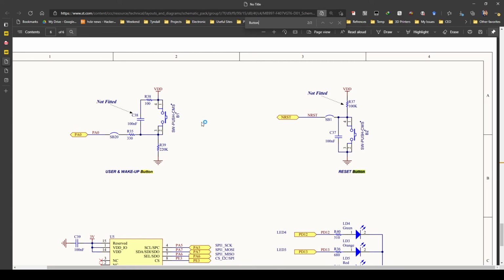And when we release the button, because of this pull down resistor here, the 0 value will replace whatever we had here. So I'm going through it again.